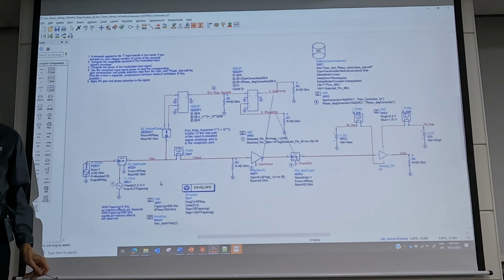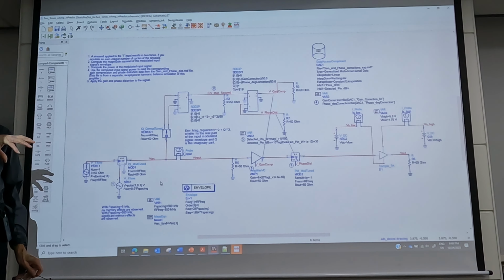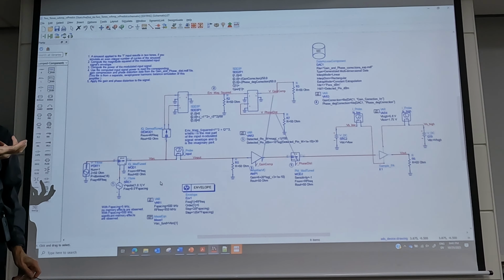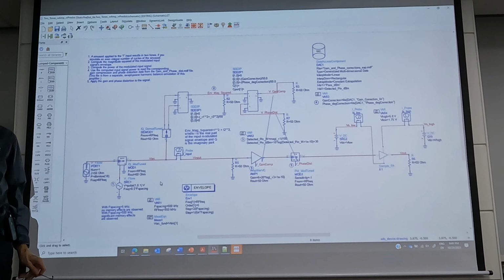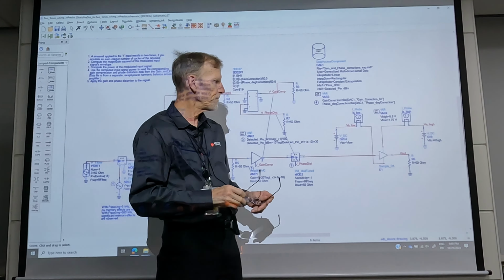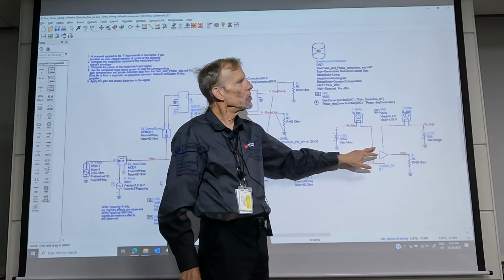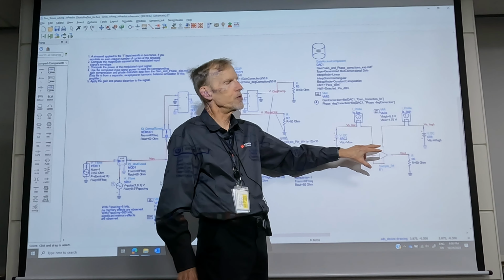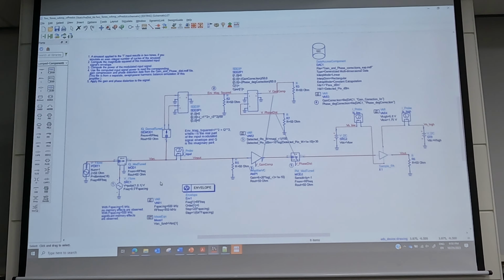Okay, so yes, ideally what you'd like to do is apply a more sophisticated pre-distortion algorithm. But I think this is still useful for comparing different amplifiers. If you had to compare two different amplifiers, you'd like to have the raw memory as low as possible initially. And I think this enables you to compare different amplifiers and see what the memory is for a given input signal.